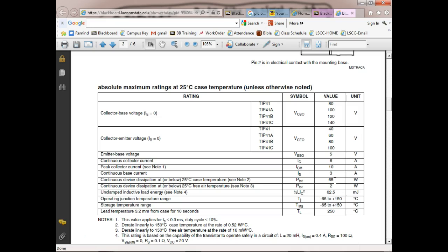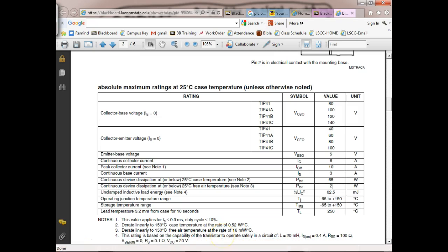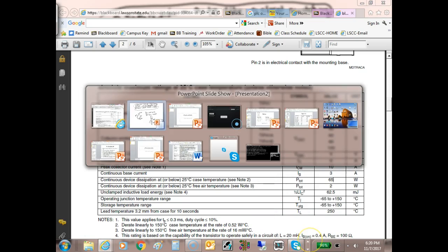It's got a minimum gain of 15. The 3904 has a minimum gain of 30. So I could use that minimum gain of 30 and run it into this, and what would be my total gain if I hook this thing in a Darlington arrangement? So what does that Darlington arrangement mean? You're going to run into this a lot too. Because what do we get when we hook up a Darlington arrangement? We got several features of this.